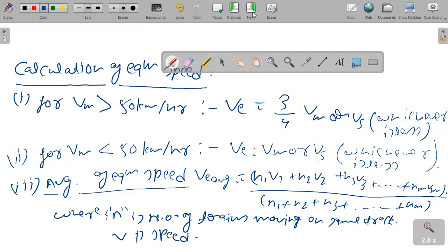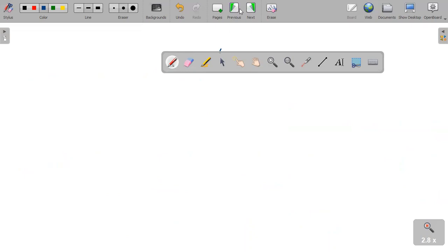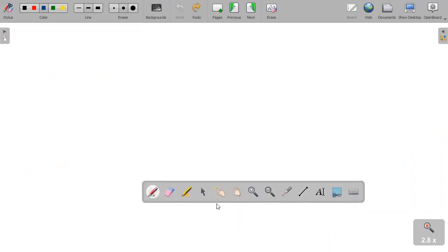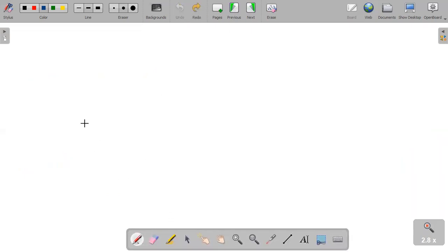Let's move on to the next thing, which is limits of Cant. So for broad gauge, for group ABC routes, it is equal to 165 mm, and for group D routes, it is about 140 mm. And for meter gauge, it is 90 mm, and for narrow gauge, with same condition, it is 65 mm.